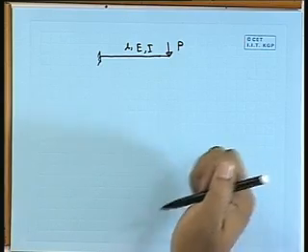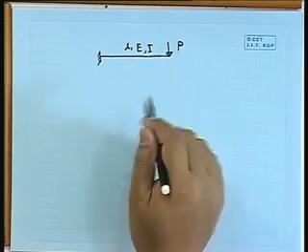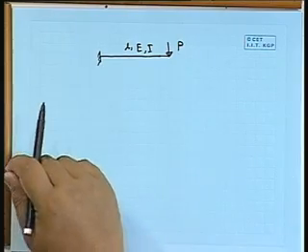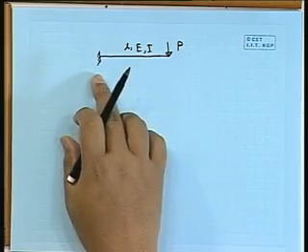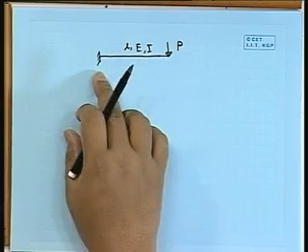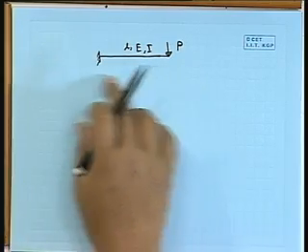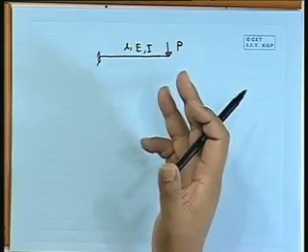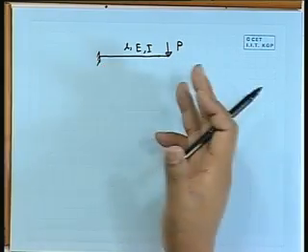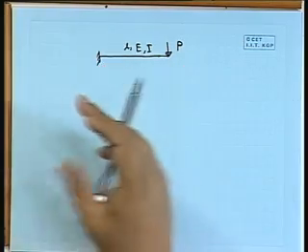So, the first job is to find the expression of the bending moment. Now, you can start x from this side or from that side. It is better to start from this side because the expression will be much easier, P into x. From the other side it will be P into L minus x.